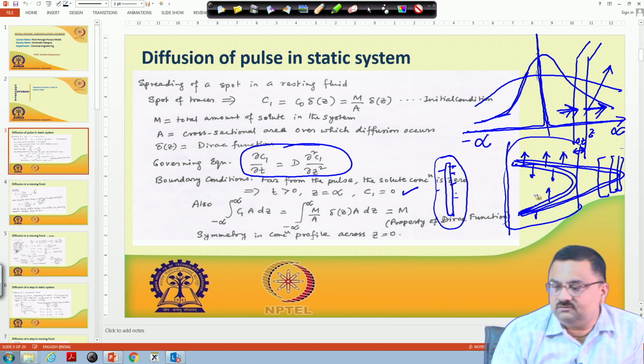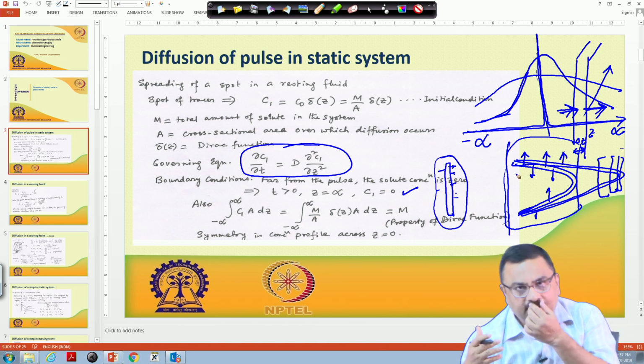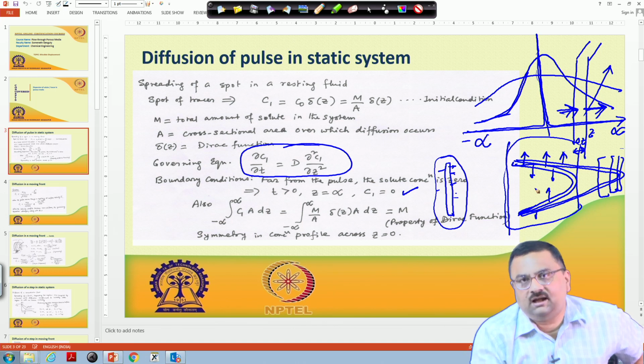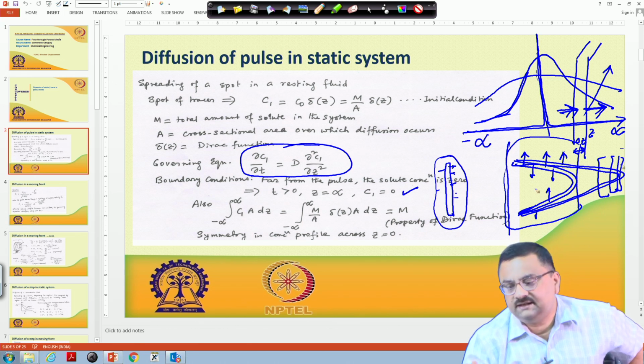When your strip is maintaining its form as a strip, it will continue to expand like a parabola, and you are creating a much larger mixing zone. So when the diffusion coefficient is less, essentially you have a larger dispersion, because at the end of the day you are collecting it in slices from the sides, and these slices are mixed and you get this concentration.